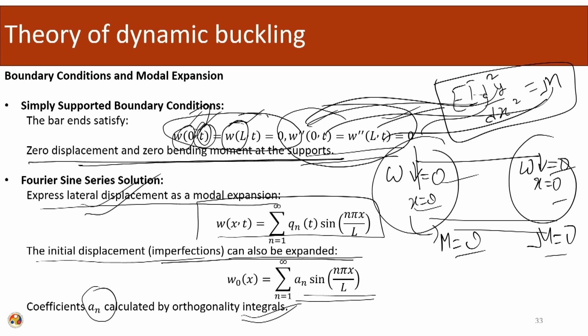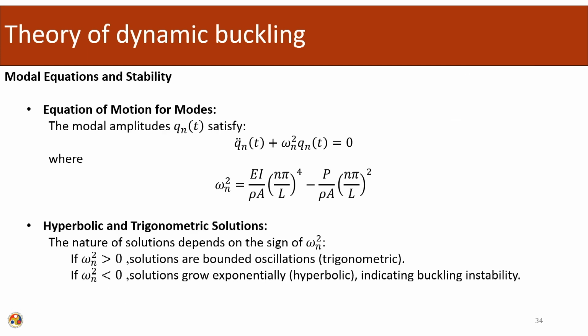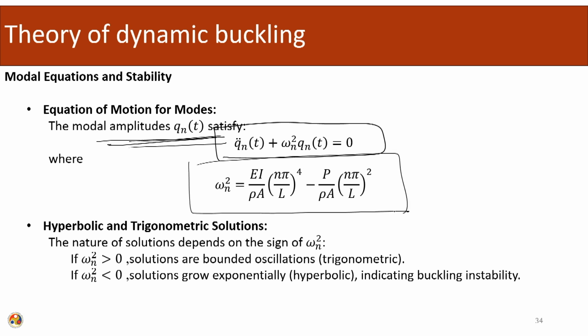Once we have done all this, the equation of motion can be decoupled using modal orthogonality, and the decoupled equations of motion for different modes are given by this term, where omega n gives us the frequency of the system.